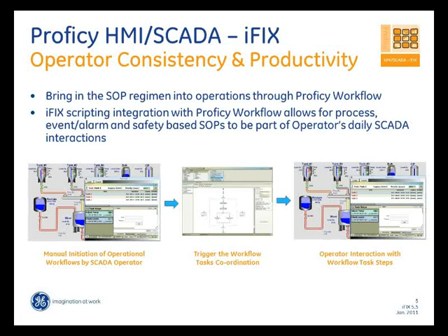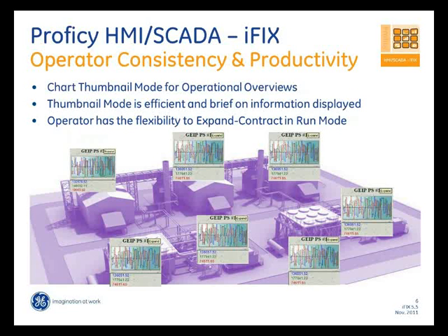The other aspect is related to charts. We introduced this chart object when we did iFix 5.0, but we have done several enhancements to that chart object. The first feature is really introducing a thumbnail mode for that chart object, so you can have a small thumbnail of a chart which basically updates as data comes in on your screen, and you can have multiple of these thumbnails on your screen. There are customers, especially infrastructure customers, who have their facilities over a wide geographic area that put these thumbnails on a geographic overview, and basically operators look at that and use that as a navigation tool in case they see the trends not going the right way. So that's one aspect that we introduced.